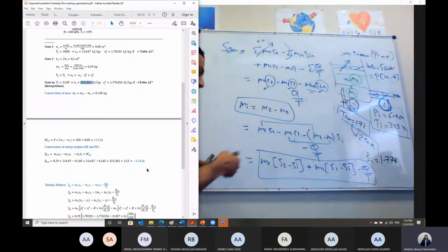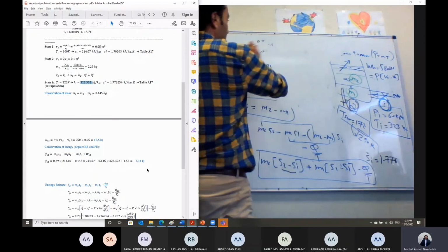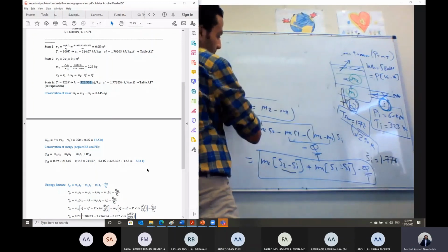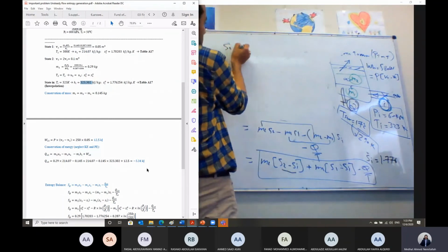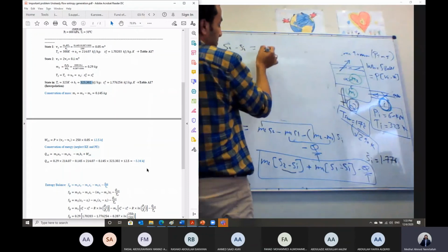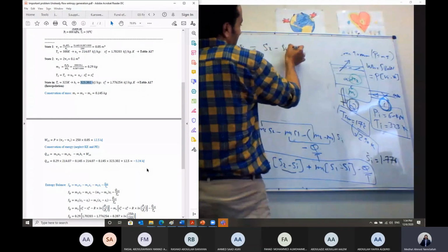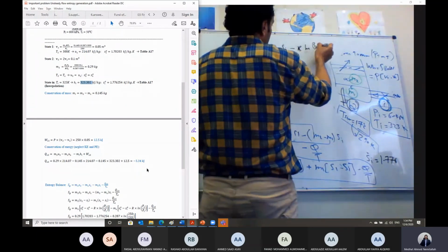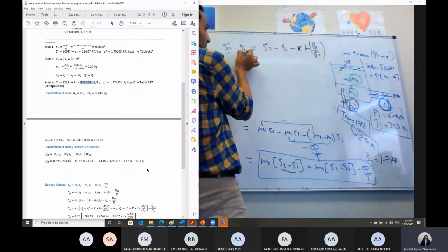Now this term, following the exact analysis, S2 minus S inlet will equal to what? Now we have an equation in which we have delta S, so now it can be solved. We can say S2 minus S inlet will equal S naught 2 minus S naught inlet minus R ln P2 divided by P inlet, because we talk about state 2 and the inlet.